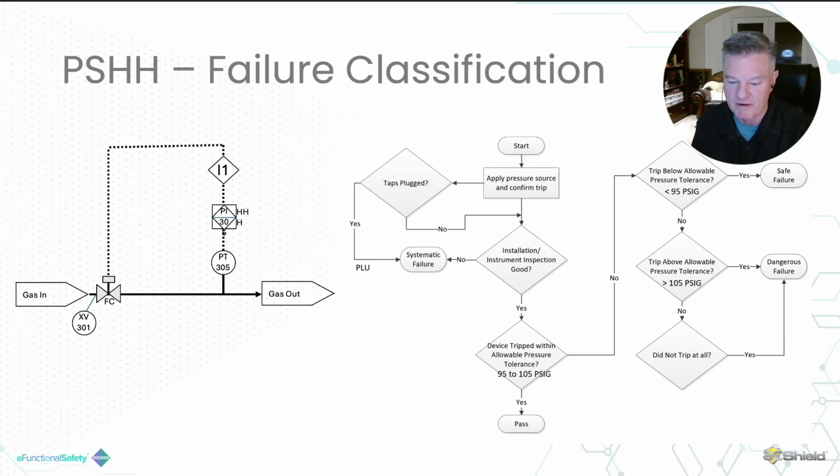There's a Nomura white paper on valves. And basically, if you look at what Nomura has done with their white paper on valves, valves never fail. I think it's like 2 FITs, 5 FITs, some ridiculously low number, because if it doesn't close fast enough, it's my fault because I didn't specify enough torque or high enough instrument air pressure. If it leaks, it's my fault because I specified the wrong material of construction for corrosion and erosion. So that all sounds good, but if I'm not changing that valve out, and that's the same valve we're going to use forevermore, well, those are not systematic errors. They're going to be things we're going to see continuing through the kit, and you'd have to deal with that.